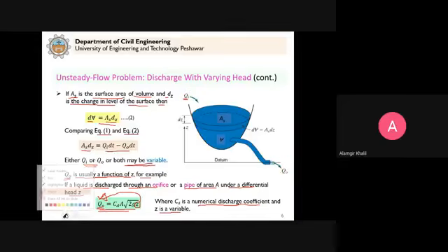Next, let's say, for example, if we have a weir or spillway, then in that case, this is the equation that you have studied in the flow measurement chapter in Fluid Mechanics 1. So Q0 is equal to C L H^(3/2) for a weir or spillway.